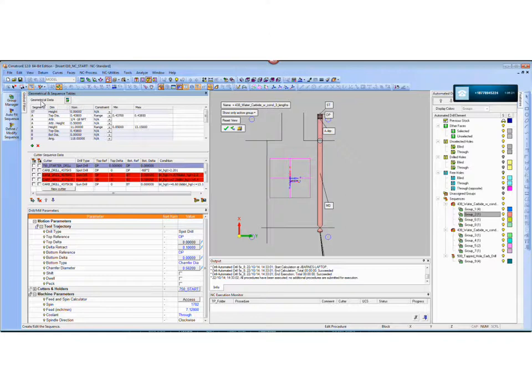And I can set a condition that says if there's stock on the top of the hole from 0 to 100, let that be a condition for it fitting to this geometry. Or I can say, don't worry about the stock. I'm not concerned about it. You also can set a range, and you can say that this is using from 437 to 438 and 5/10.